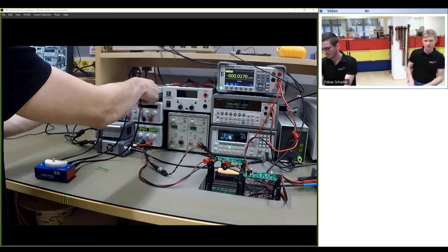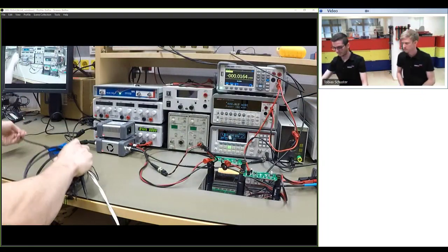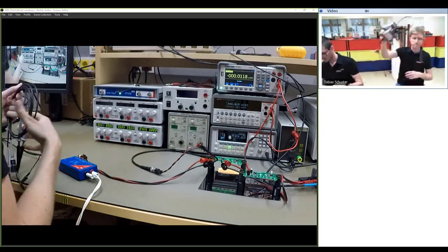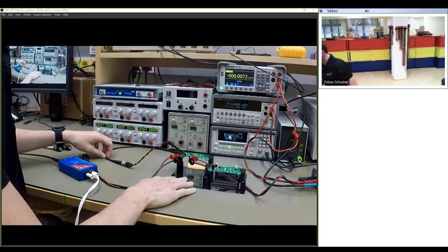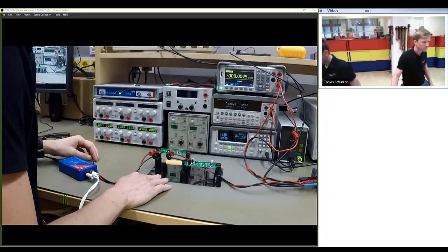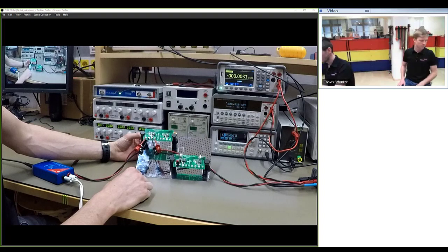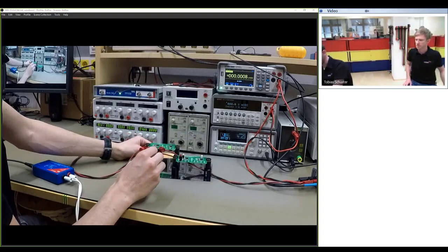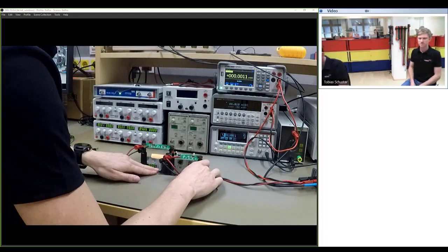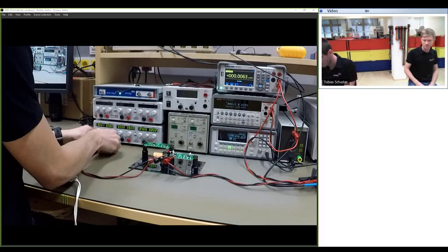So Tobias, can you please change the setup? So let's get rid of that one. So now I don't need that probe. We now will use the second port on the bottom side, since there we already have an injection resistor connected, so that I can do a loop gain measurement. So we'll connect the loads to the second port, and then we will connect the input voltage from our power supply.